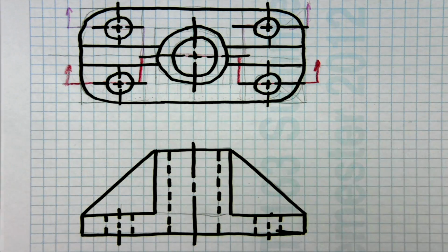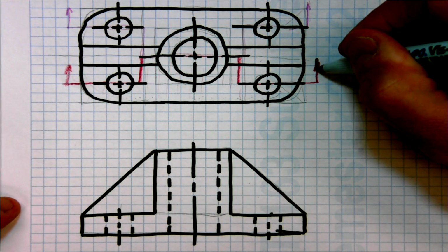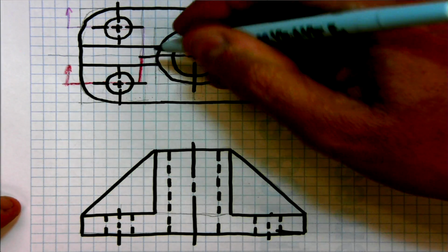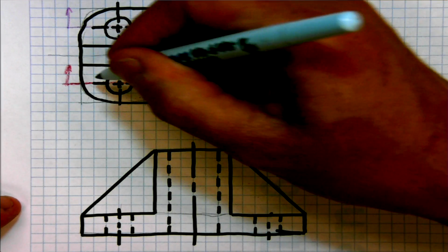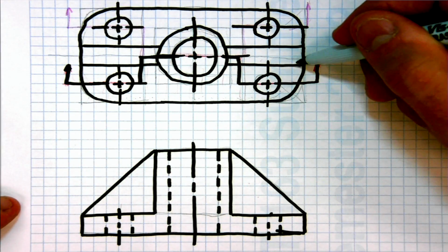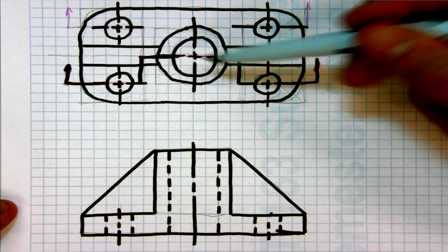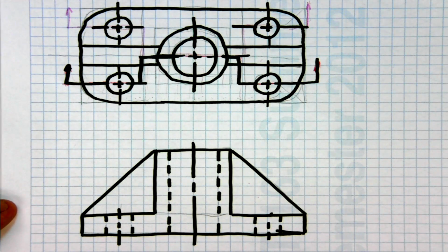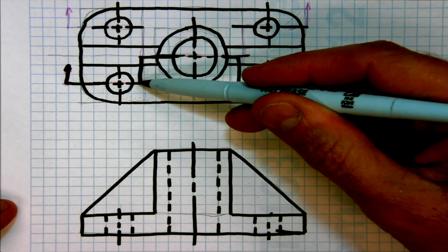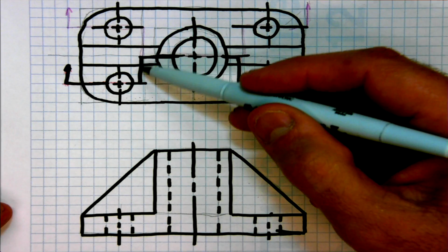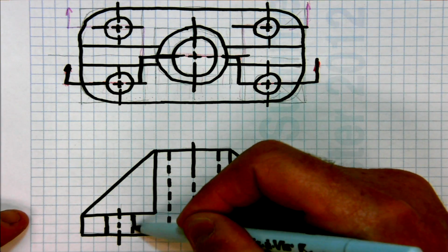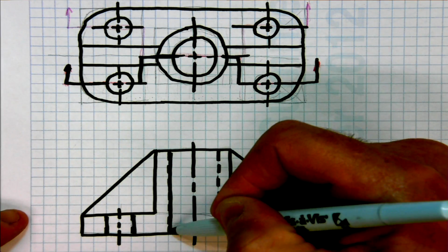So the best option on this one would be to take an offset cutting plane, go through here, turn it, go through here, turn it, go through here, and up. That way you don't remove either one of these ribs. And remember, these support features are not crosshatched. You've used a full offset cutting plane. Remember, here's the offset here, going back, offsetting towards the front, and so on. There's no change of plane where it offsets, so now this has been exposed. These are now all solid lines.